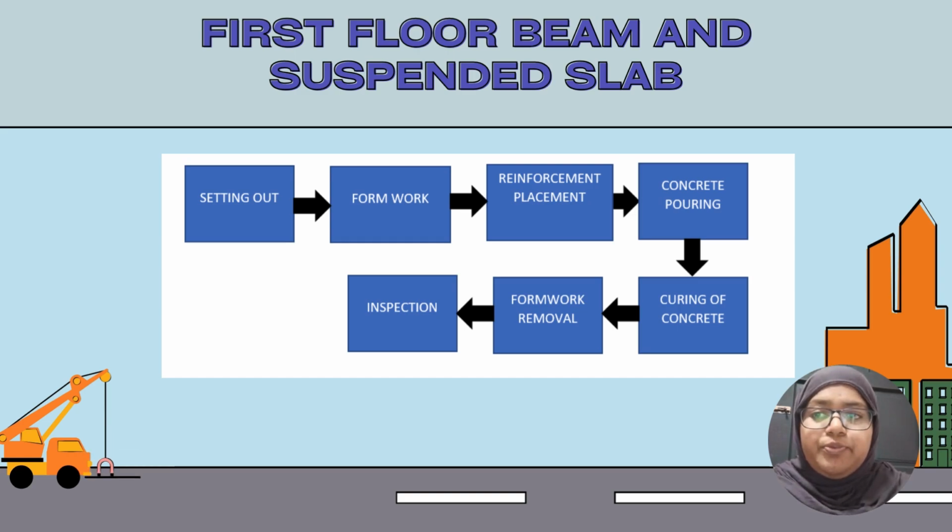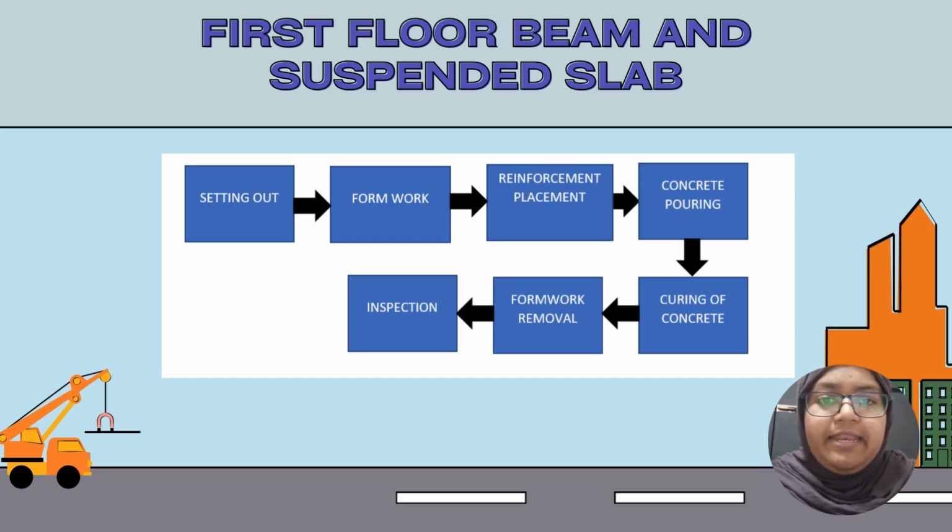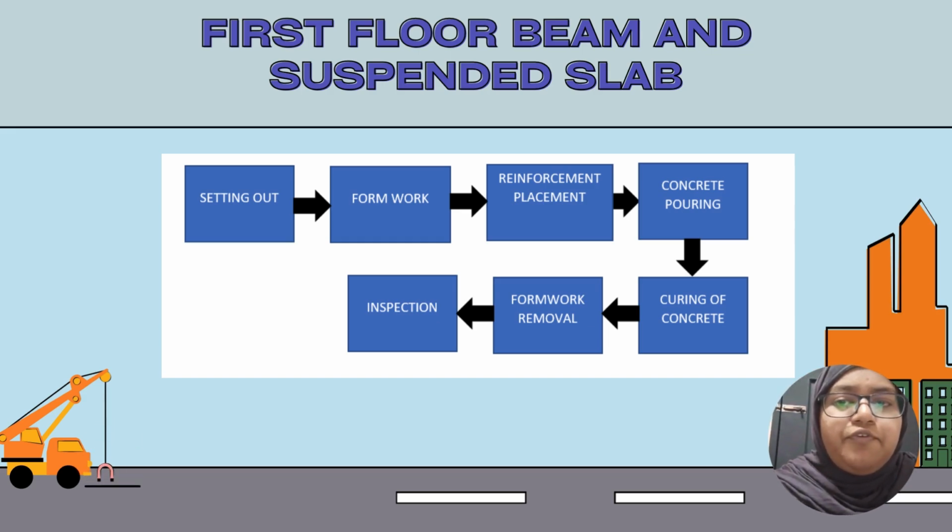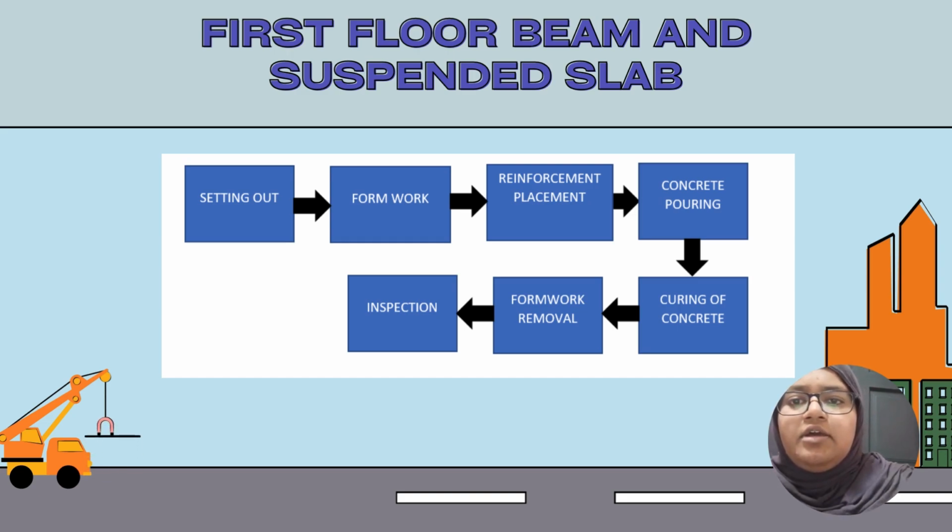Okay, for concrete pouring, ensure that the formwork for both the beam and slab is secure, level and aligned. Check for any gap or misalignment that could cause the concrete to leak or set unevenly.